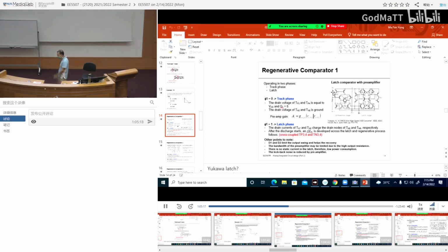First advice is that you always look at where the input is and where the output is. And this is very important: when you draw your schematic, please draw it in a logical way. That means input comes from the left, output goes to the right, or input comes from the top, output goes to the bottom. There must be a certain structure. You don't mix your circuit with inputs left, right, up, down, as that makes it very hard to read.